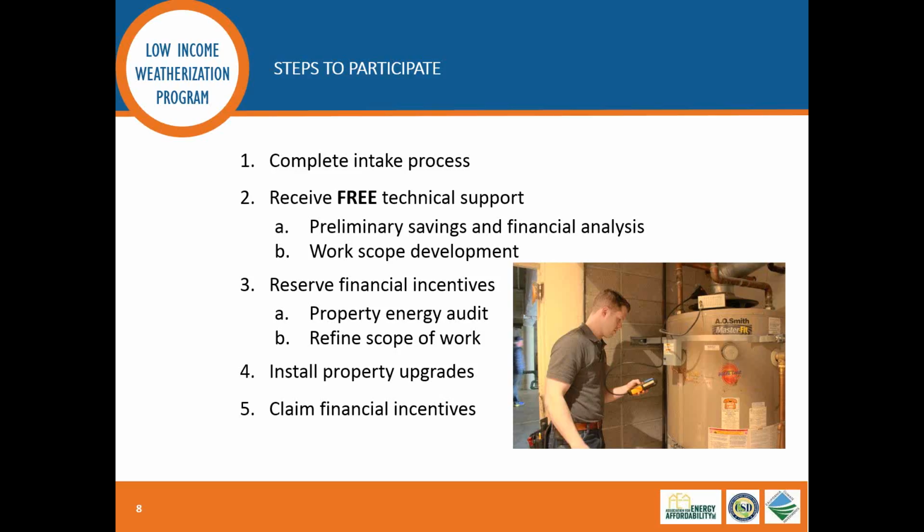Then the owner hires the contractor that they select, and from that point on it's your typical construction process. So we would want to make sure that, A, your proposal is complete and that you recognize all the requirements for that scope of work, and then B, provide submittals for the various materials, provide a construction schedule, those sort of things, with regular check-ins as needed, ultimately just to make sure that the program's on track.